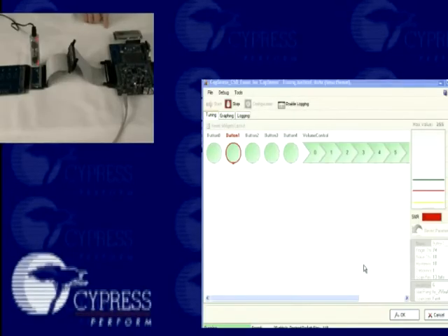So I'm using the same -030 board, the same silicon, and I did not reprogram the board again. The only difference I made here is to add this ribbon cable, which is 18 centimeters long. And then let's see the CapSense performance after we add the ribbon cable without changing any firmware and debugging development process. On the screen here, you can see the GUI is running, and I'm pressing my finger on the slider and then pushing the button as well. So we added the ribbon cable, and then let's see the SNR rate on button number 1.